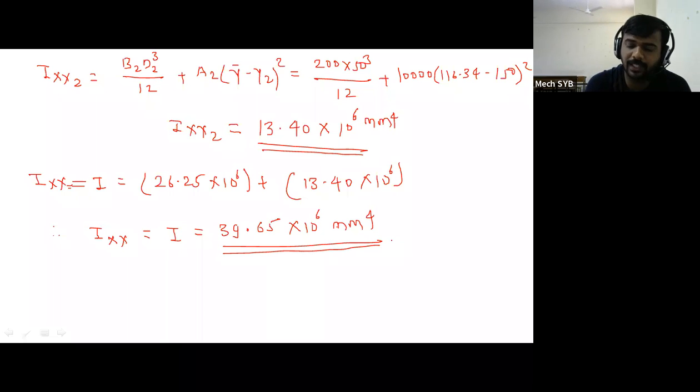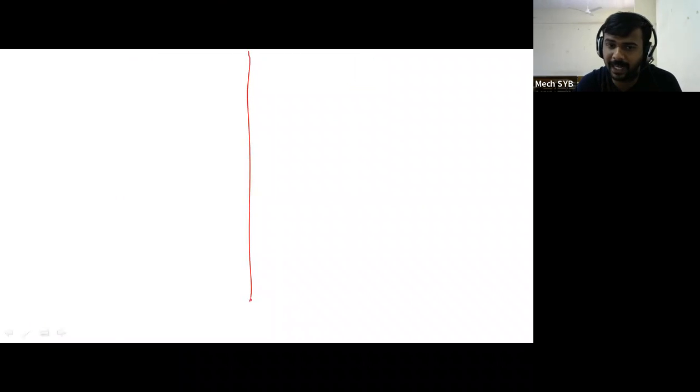Okay, now moment of inertia is calculated, y bar is calculated. Bending moment we have calculated, so we have to use the formula. So we have to use the formula and we have to calculate the bending stress value and we have to decide the nature, that is, we also have to decide the nature of the bending stress value obtained.